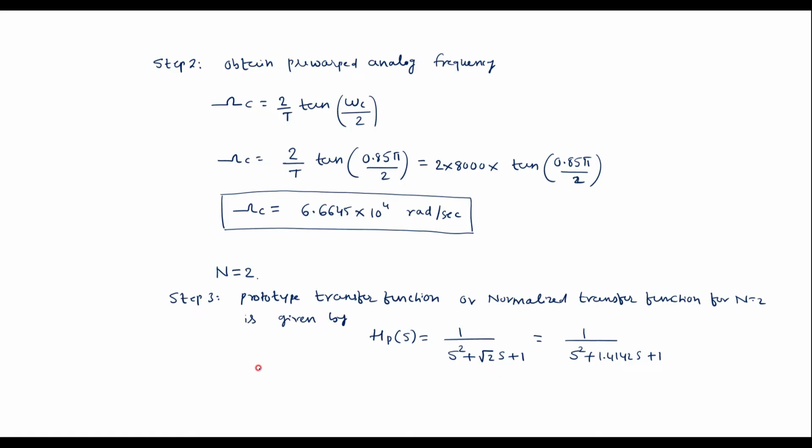So now we know that to design the digital filter, first we are supposed to design the analog filter. Then by using digital transformation method, we are supposed to convert analog filter into digital filter. So with the help of prototype transfer function, now we'll design the low pass analog filter. Let that be our fourth step.